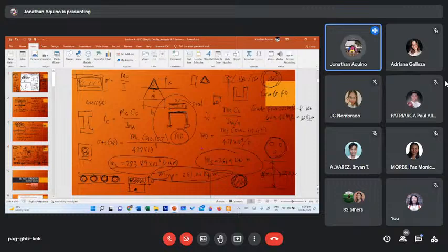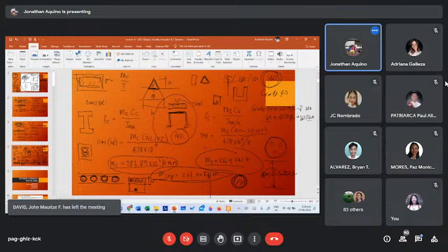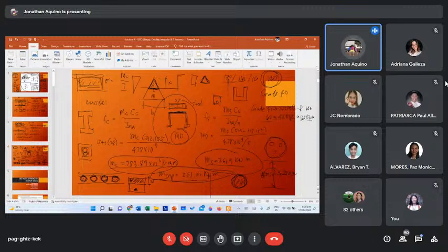So here, we assume that the stress distribution is linear, but in ultimate strength design, the stress distribution is parabolic, not linear anymore. Because the stress at the top is different from the stress at the bottom, so it is just triangular. But in ultimate strength design, it's parabolic. Starting from this stress, as you load it, it grows until it reaches the point where it peaks. Near failure mode, the stress near the neutral axis decreases. But in parabolic, it's a parabolic curve, not anymore triangular or a straight line.